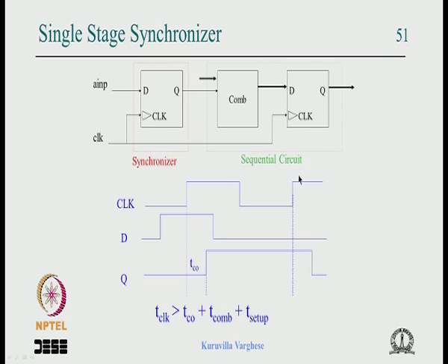Some could be 1, some could be 0, some could be in metastability and so on. Though the way I say it, you might think that it occurs so frequently, it doesn't. But I want to highlight the problem of sampling an asynchronous input at multiple places with different path delay. Okay, that's the issue.